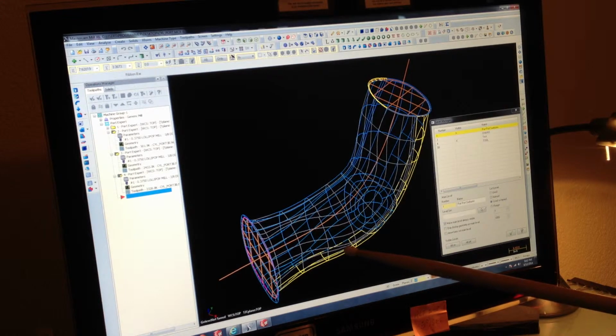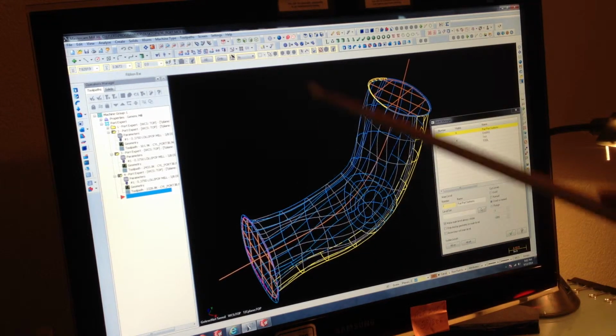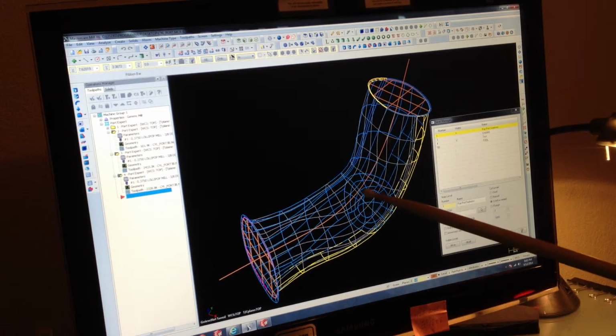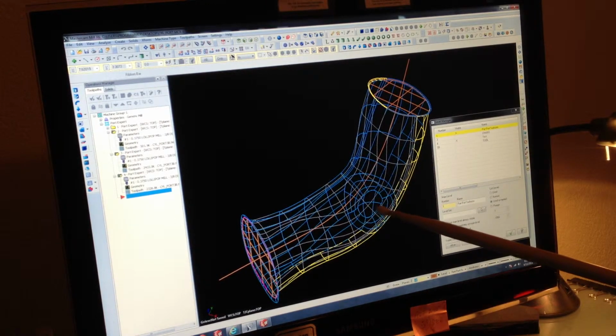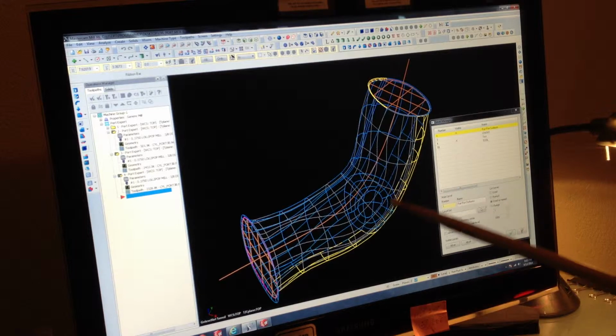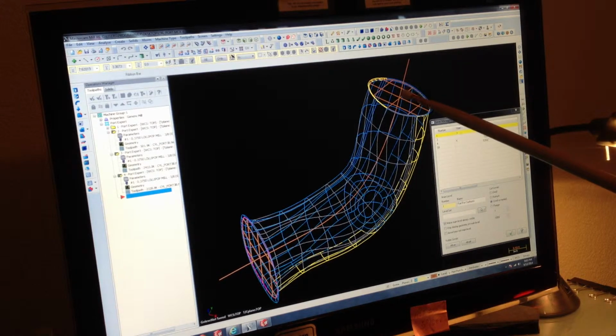So if that happens, I would delete the spline first. I'll try to recreate it and go to that little section right there and change your control of your spline. Over here, the curve goes up and down a little bit at a time. Or another thing, if that doesn't work and you still have an alarm, you have to delete the spline and both vectors, and recreate the vectors. And when you create the vectors, you've got to stay up in front, in the center. You move a little bit to the right, a little bit to the left.